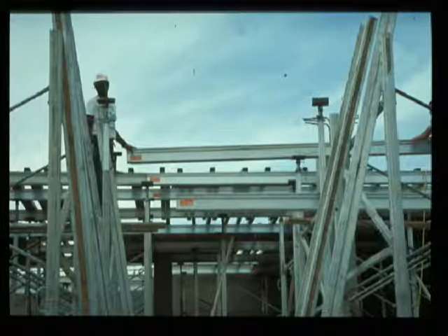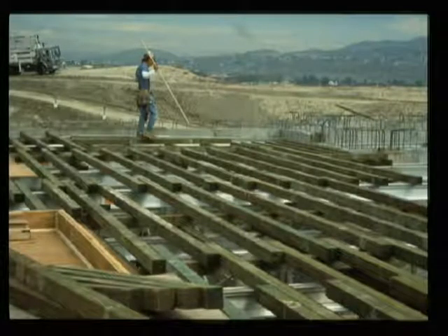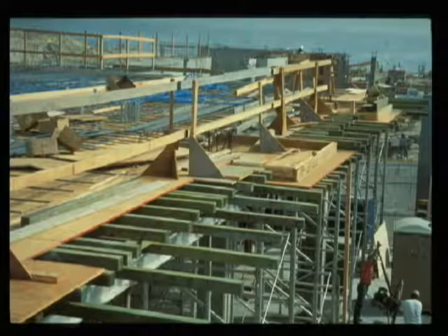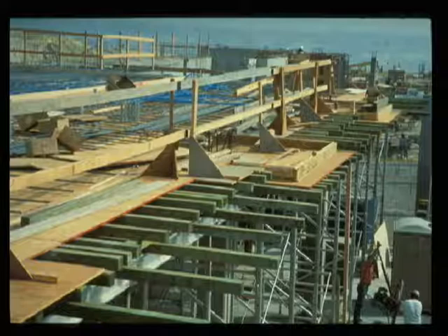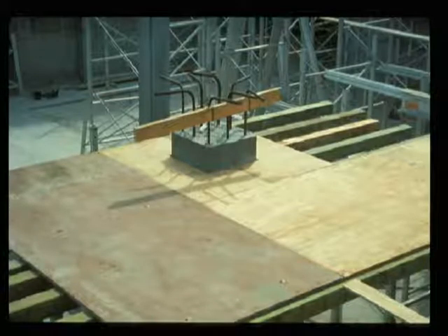This image starts the flat slab construction section. Aluminum shores and beams are used. Wood timbers are placed on top of the beams. Plywood is then placed and forms the flat slab bottom. Notice the temporary guardrail. Around the columns, the slabs are thickened to form a drop panel.